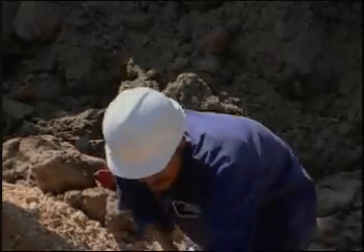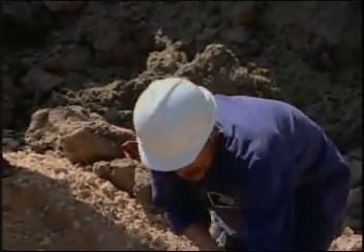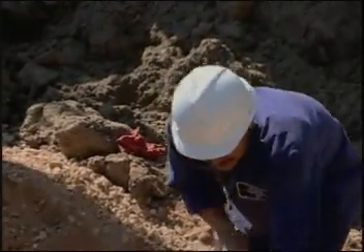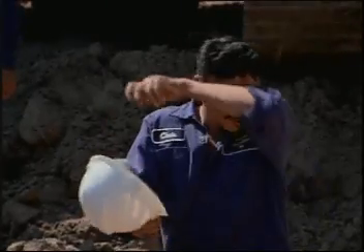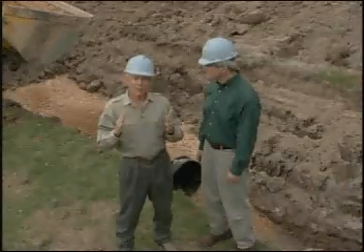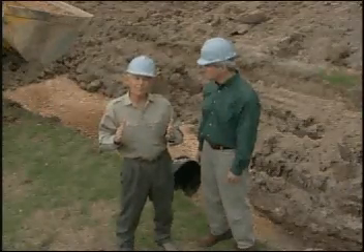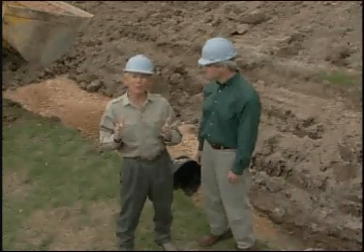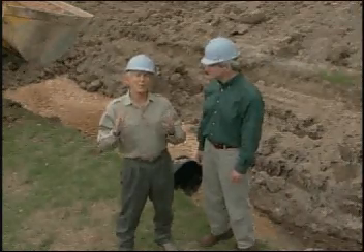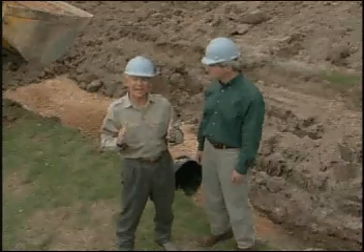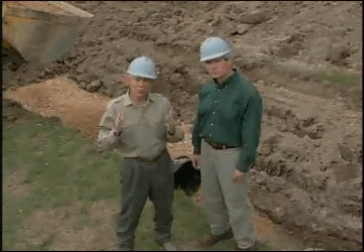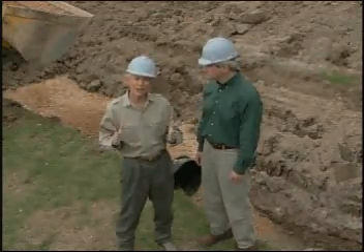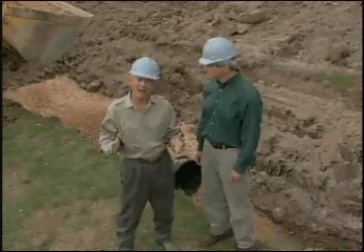It's common for a flexible pipe installation to require substantially more time than that required for the installation of rigid pipe. The relative weight of concrete pipe helps maintain its position without risk of flotation. The shorter lengths of pipe facilitate both grade alignment as well as simple and safe trench box techniques where required.